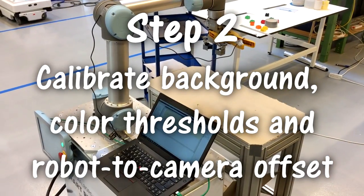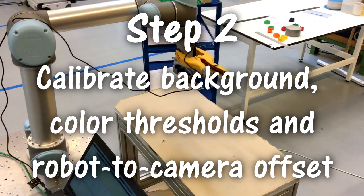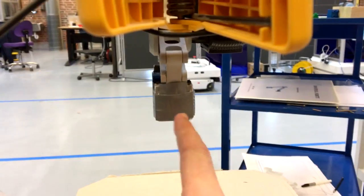The next step is to calibrate the background for removal and to calibrate the color thresholds to be used in the segmentation, and finally to calibrate the camera to robot tool offset.